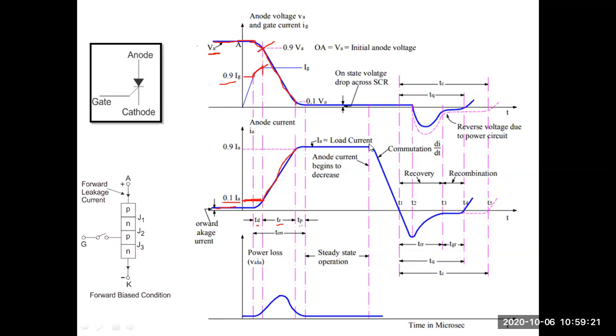As I said before, once the switch is completely closed, there is no control over the gate terminal; it is no more helpful. Then how can we bring back the forward conduction state to the forward blocking state? Either we have to interchange the polarities, so the anode is fed with negative and the cathode with positive, or else reduce the input voltage. Any of these methods we would have to go through, and practically it is not appreciable.